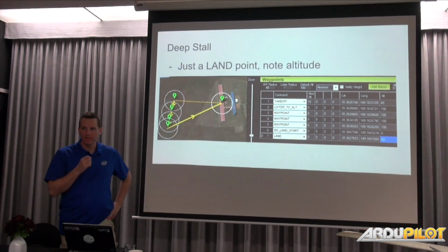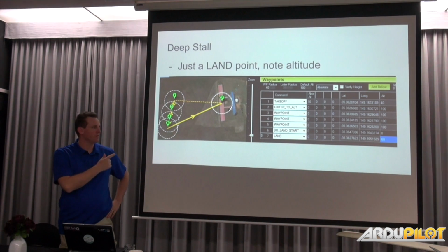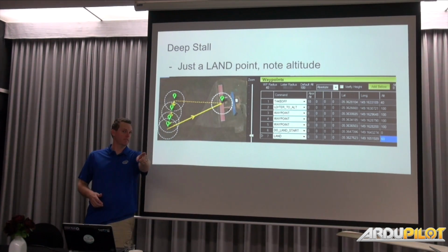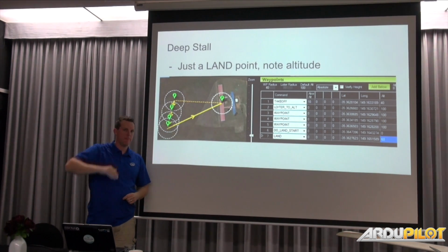It's important to note here that normally your land altitude is 0-ish, the altitude where you take off from, but the example here is 60, which was specific, because that's the altitude we like for clearing trees, and it gives us time to see it stable and doable. So that's where you actually trigger the script altitude start, that's the whole approach.